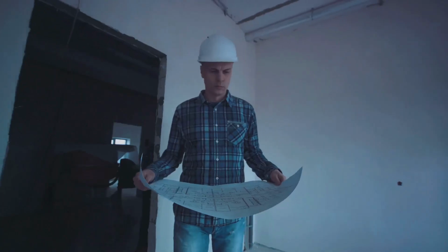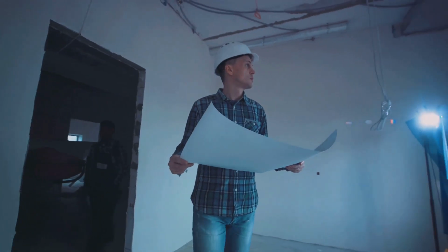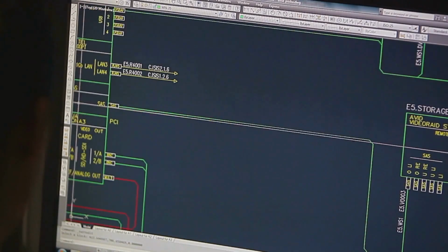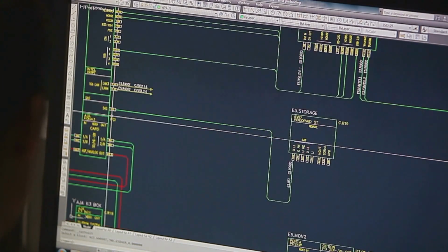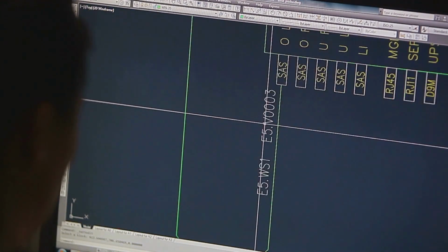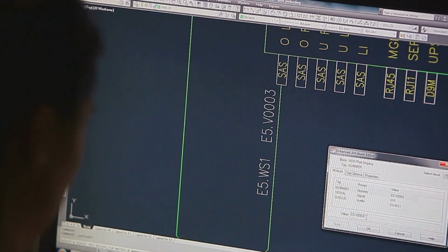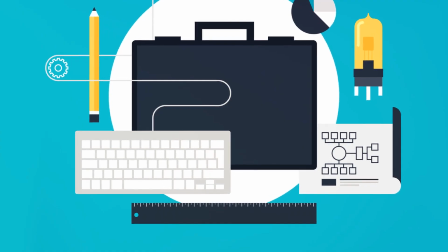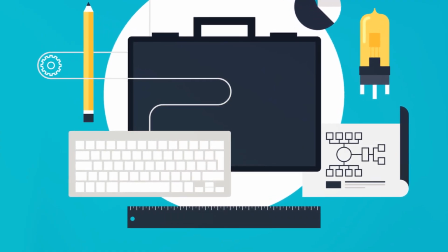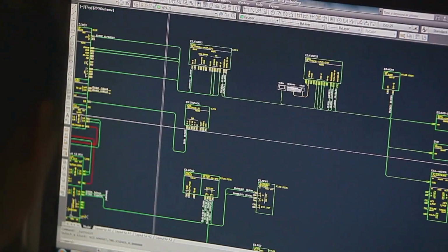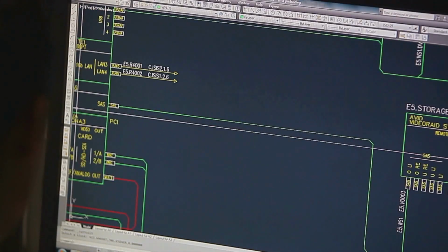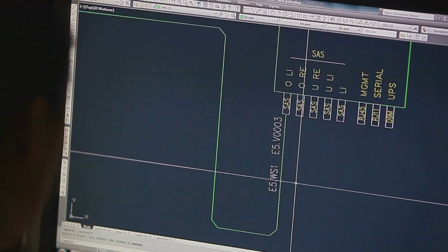This is the essence of multiple successor logic. The construction of the building structure can't wait for the elevator shafts to be finished, nor can the setting up of internal utilities wait for the building structure to be completed. These activities must run concurrently to ensure the project stays on schedule. The key is to manage these activities in a way that they don't interfere with each other, and that's where our multiple successor logic comes in.